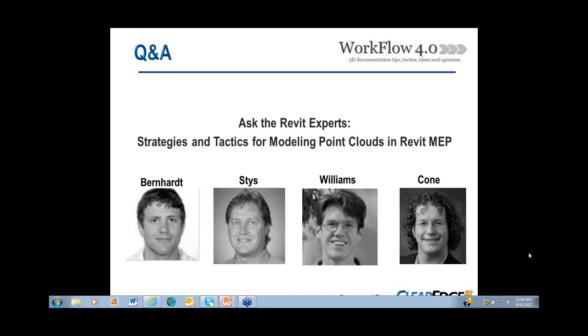Okay. And Mike, here's a techie question. It says, how exactly do you control the element position when you insert it in the Revit model? Well, I guess understanding what the origin point is going to be, when that's established right up front, then we don't have geospatial coordinates in Revit, which is, of course, coming along hopefully in the near future. So we'll create an origin point and match that up with our extraction out of anything that we create, and it comes in the right spot. As long as we have the origin point and the bearing or the angle, it'll come in.